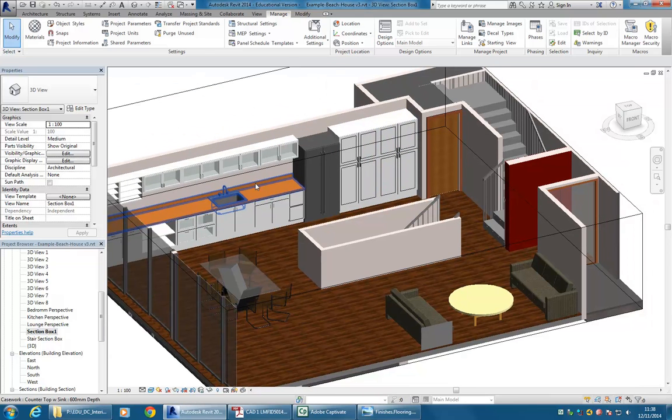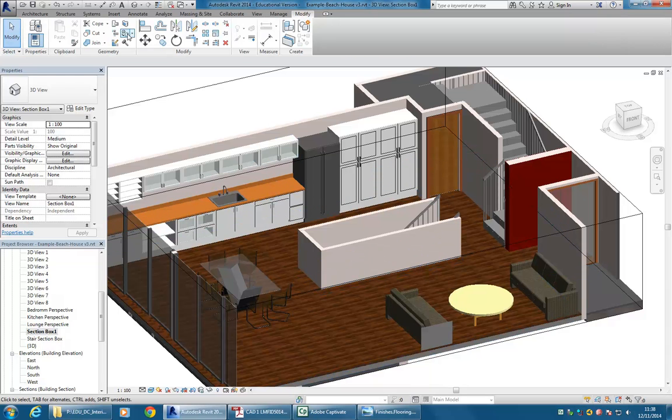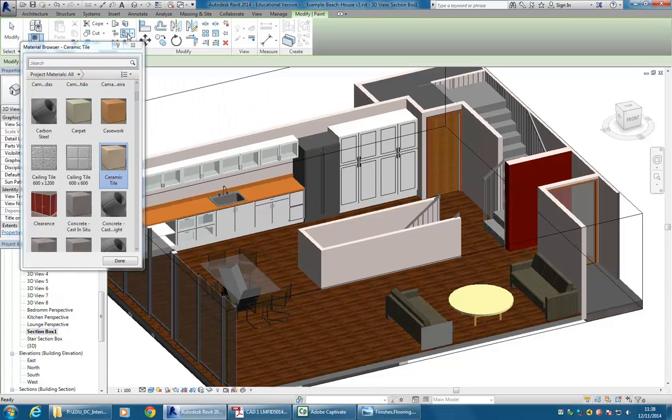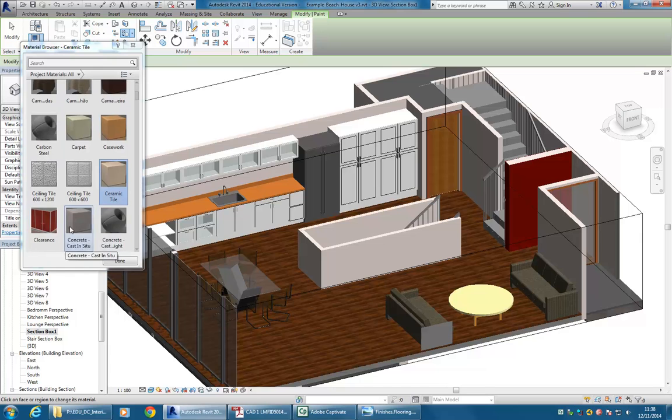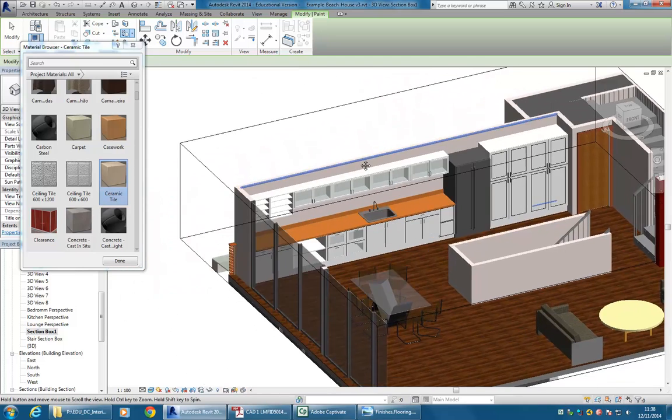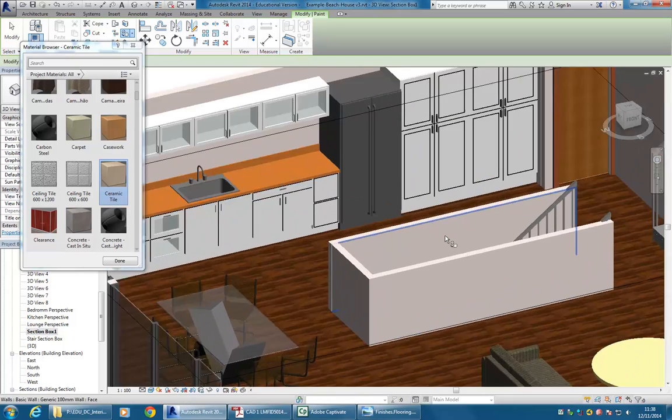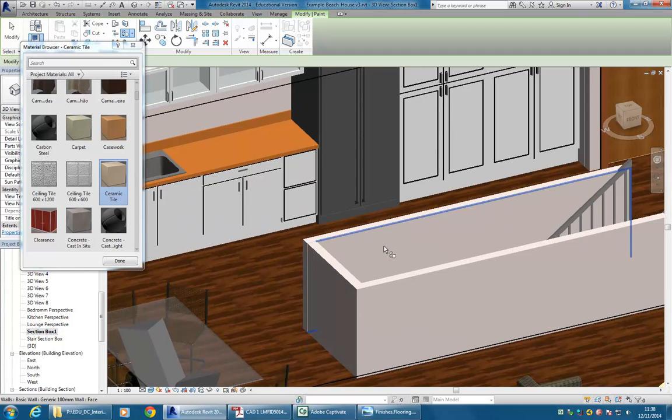Does it always have to give them thickness on the outside of the painting? Yeah, you do. If you want two different materials, you have to give it thickness. But there's one other option actually. On the Modify tab, you'll see there's a Paint option. With Paint, it'll bring up a panel where you can choose any material. So you need to have the materials made in advance. But once you do have them made, then you can choose any surface in your project.